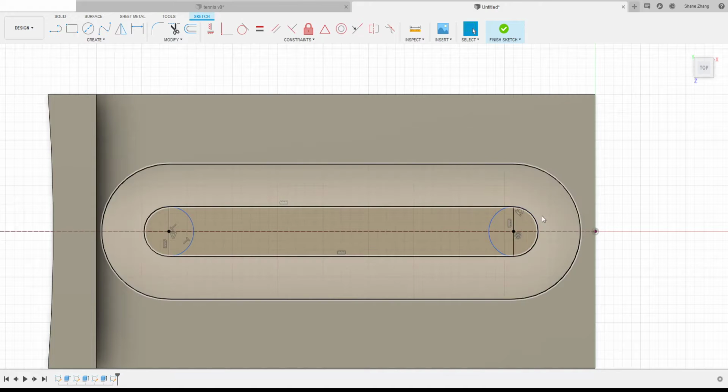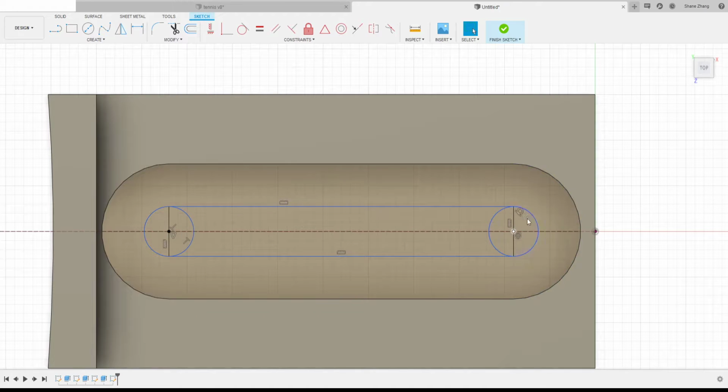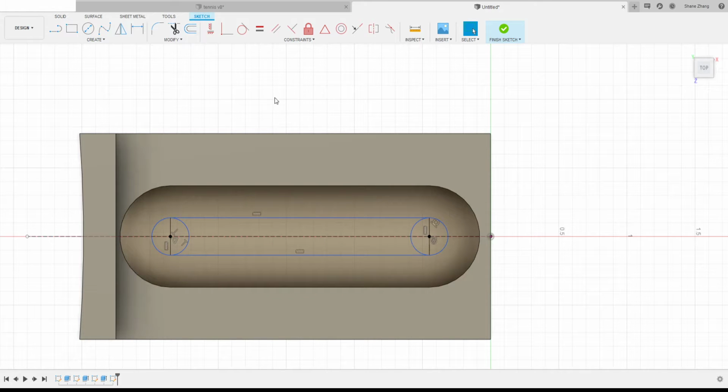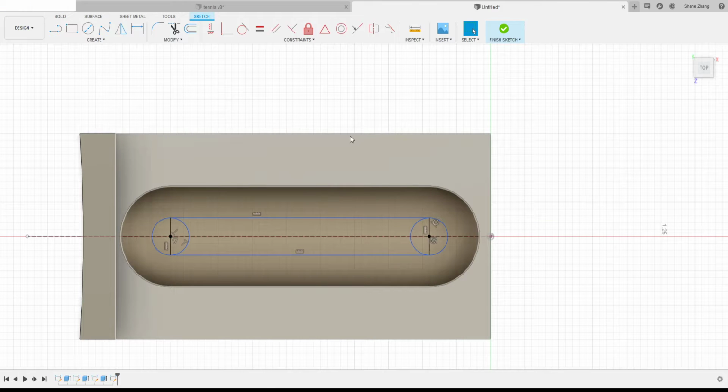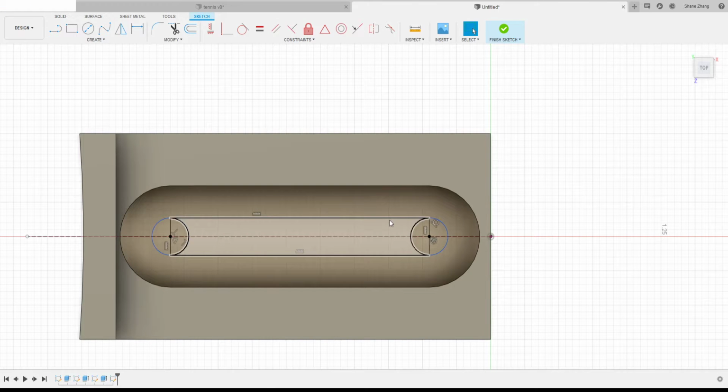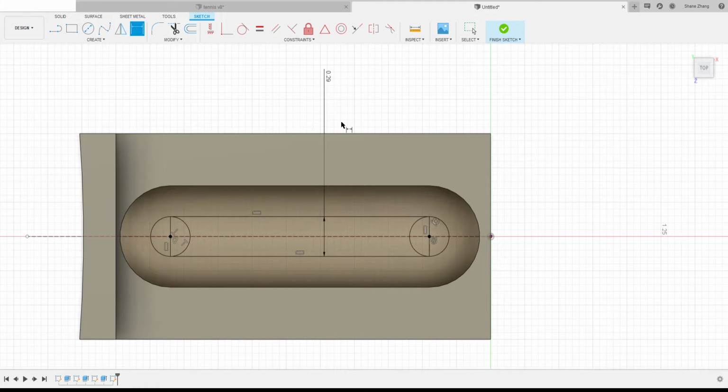And that does the same thing as concentric for 2 circles, or coincident for 2 center of the arc. It is the same result. And the width. Yeah, so when you're doing a sketch, there's a lot of different ways to dimension it or constrain it, whichever way is more convenient, or whichever way is your preference.